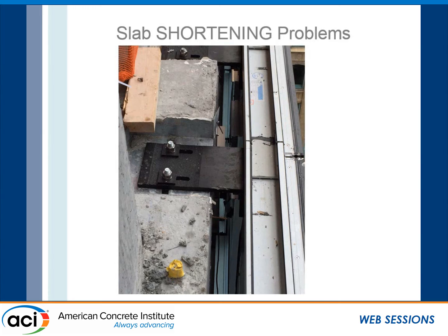And the issue here was most likely due to slab shortening due to the post-tension forces acting on the slab and causing that whole slab edge to move inwards. Again, as the previous speaker in the morning session stated, it's very common to see it come in 3/4 of an inch or 1 inch.